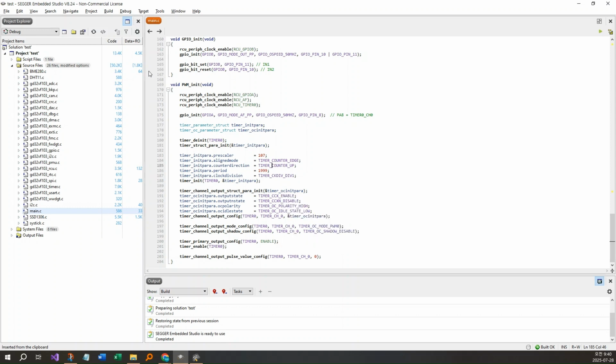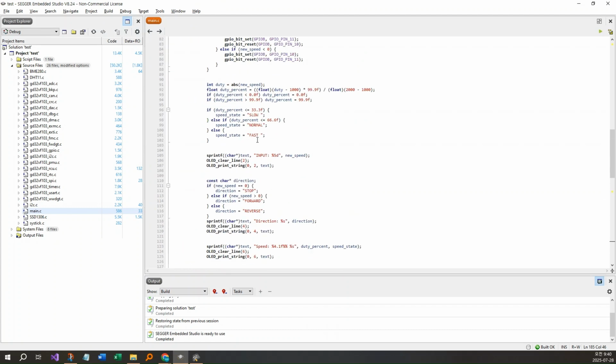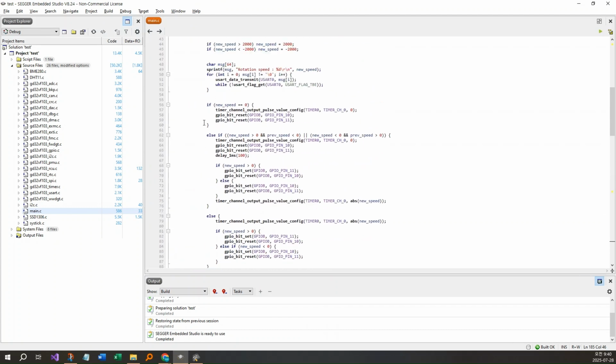and to run the motor in the setup, you need to input at least a value of 1000. And on top of that, whether the input value is positive or negative, the motor will only stop and reverse direction if the sign of the input value changes from the previous one.